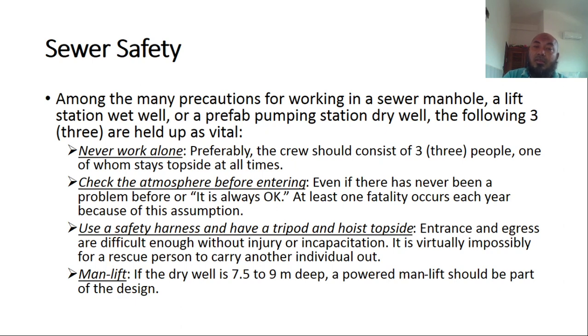Preferably the crew should consist of three people, one of whom stays topside at all times. Number two, you need to check the atmosphere before entering, even if there has never been a problem before. At least one fatality occurs each year because of this assumption.